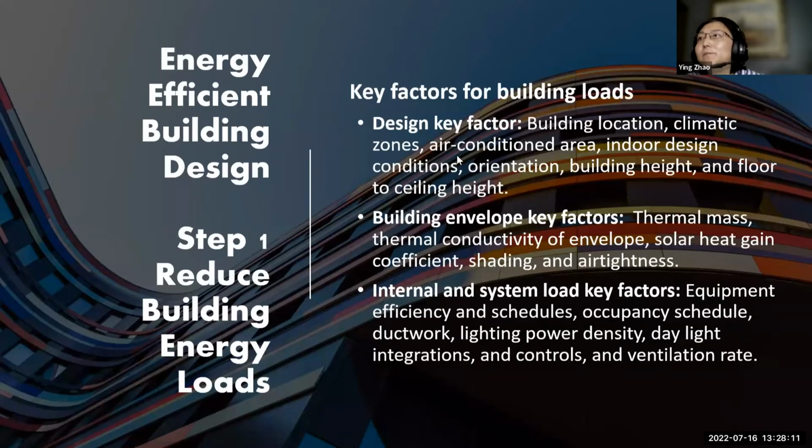The building envelope key factors are thermal mass, thermal conductivity of the envelope, solar heat gain coefficient, shading, and air tightness. There are also internal system load key factors like equipment efficiency, occupancy schedule, ductwork, lighting power density, daylight integration, lighting controls, and the ventilation rate. All these are related to the building loads.